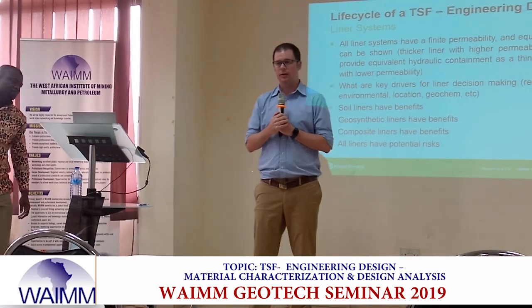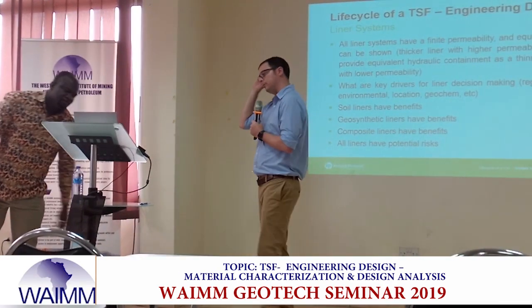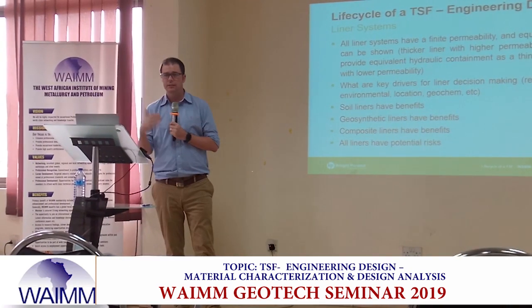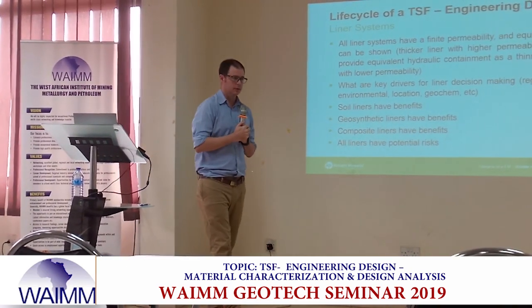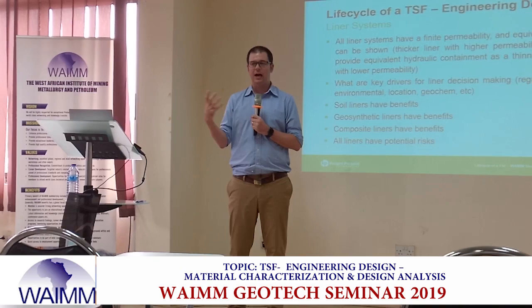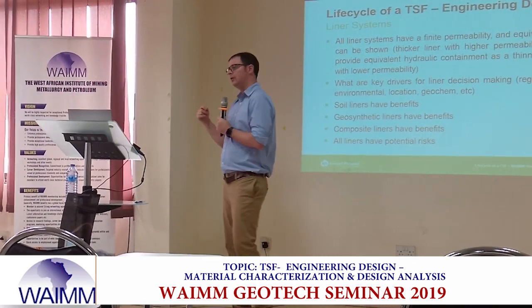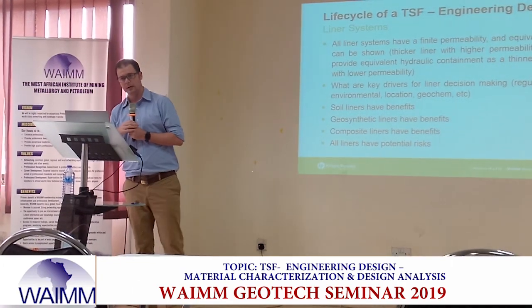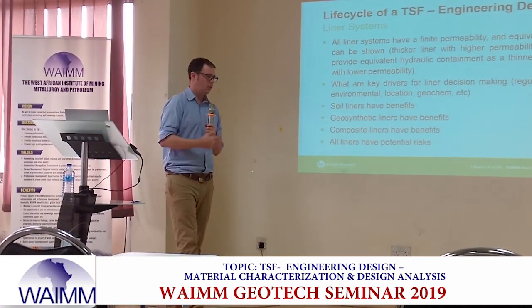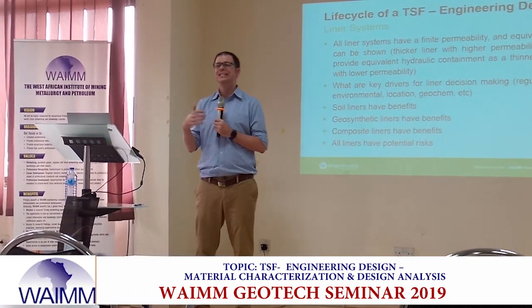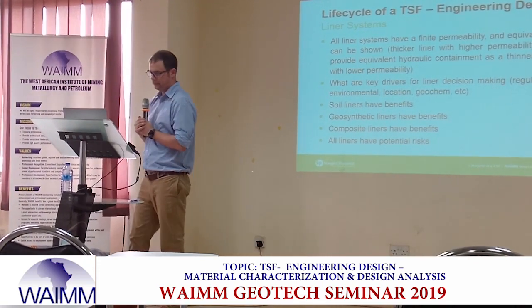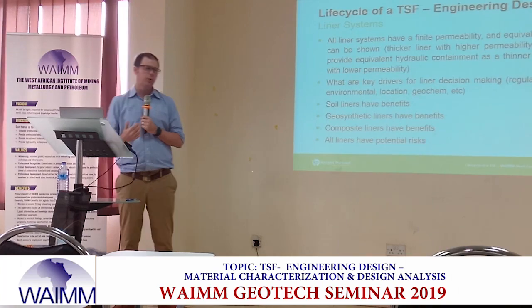HDPE geomembrane does have a permeability. It's actually referred to as a transmissivity, but it does pass water through it. Compacted soil does have a finite permeability. There is no such thing as an impermeable barrier. Okay? Concrete, water leaks through concrete. Steel, water will actually pass through steel on a long enough time. And we can look at those equivalencies.